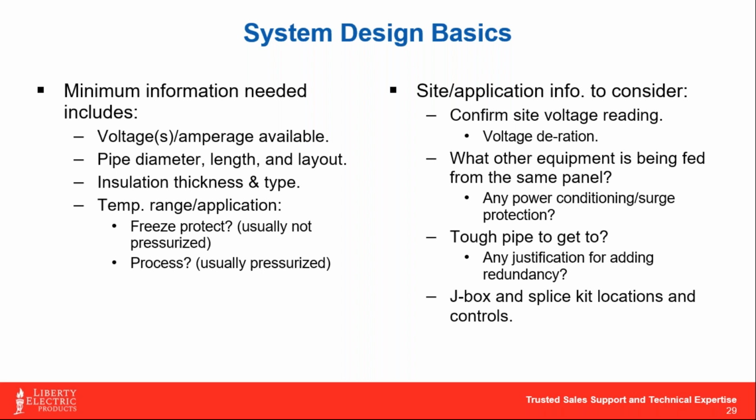So I'm just going to touch on it for a quick second. When we put heat trace cable on a pipe, we strongly recommend using linear runs down the pipe. I know a lot of people think that this stuff gets spiral wrapped around the circumference of the pipe. When you think about that for a second, to get the length you would need for a 100-foot length of a 2-inch diameter pipe, you're taking that 2 inches times 3.14.